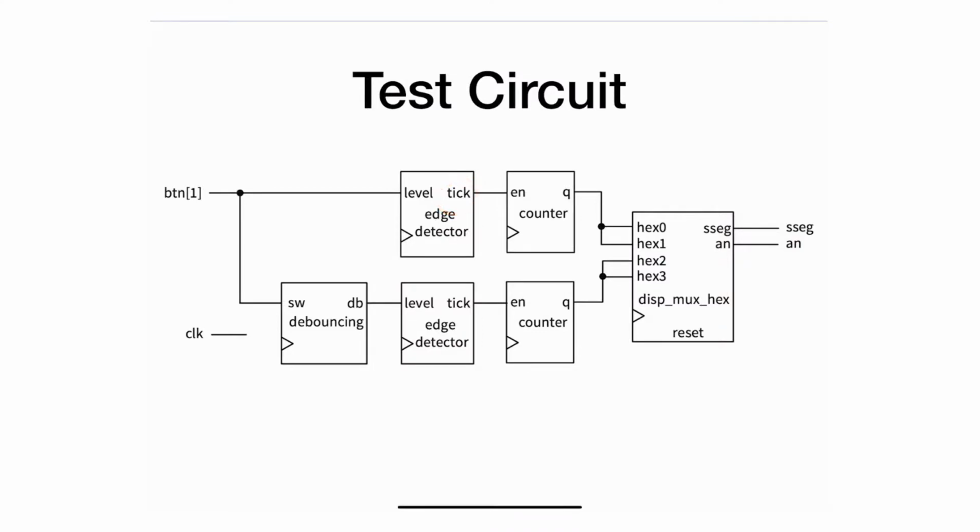This is actually not a good habit. Everything here operates on the same clock, which is 100 megahertz. The tick here might not be a good clock, and the other reason is that I will be using the Mealy output, and the Mealy output is not very stable, so that is not good as a clock. So I added a little bit of an enable here, so I'll only increase the counter if its enable is asserted. It's the same exact counter.